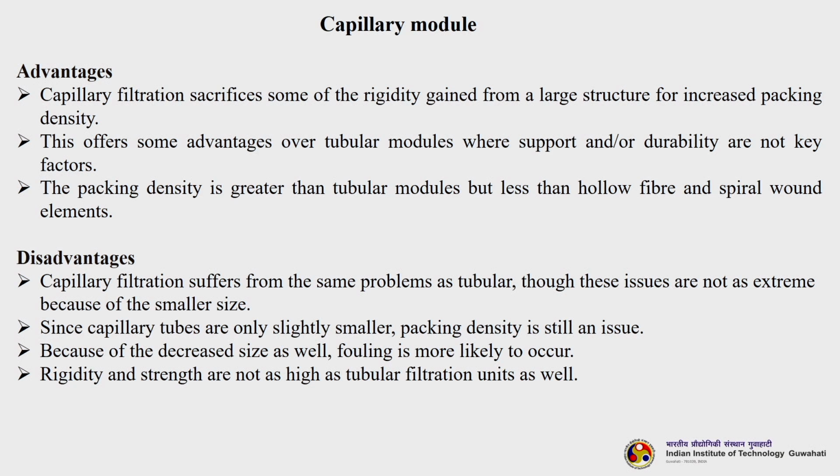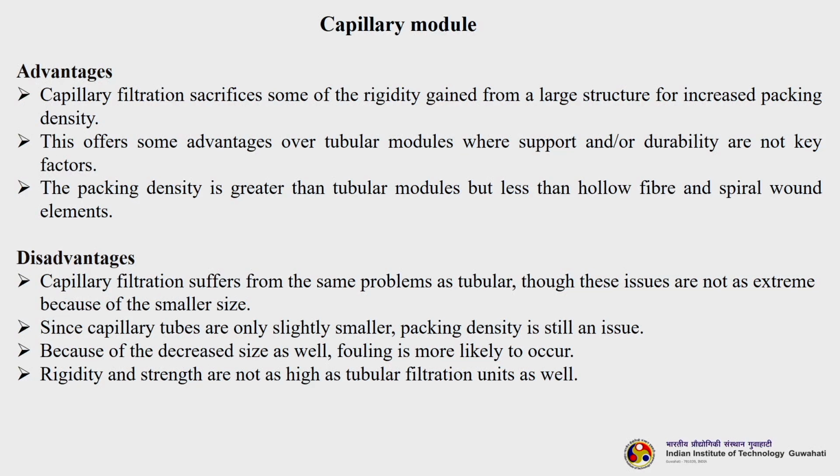However, they also suffer from certain disadvantages. The problems which are regular in tubular membranes are the same in case of capillary modules, because the sizes are also very small here. Since capillary tubes are only slightly smaller, packing density is still an issue. Because of the decreased size as well, fouling is more likely to occur, and rigidity and strength are not as high as tubular filtration units, because since they are self supporting and do not have any external support, the mechanical strength is an issue.